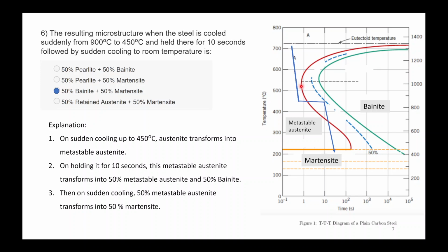Okay, so this is the starting temperature, so there won't be a start. It depends on the percentage. If you are going inside this curve, only then there will be some starting of pearlite formation. And mainly when you touch this graph, it is around nose temperature, which is for bainite formation. Touching pearlite and coming downwards is not possible in case of continuous cooling. Okay, ma'am.